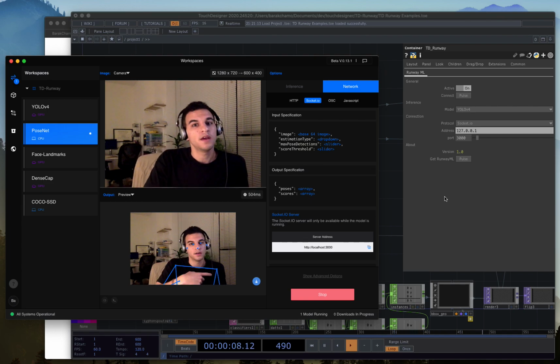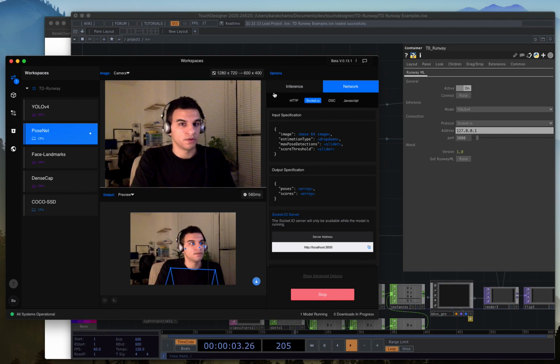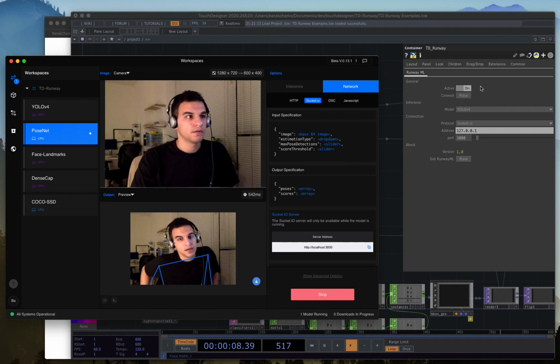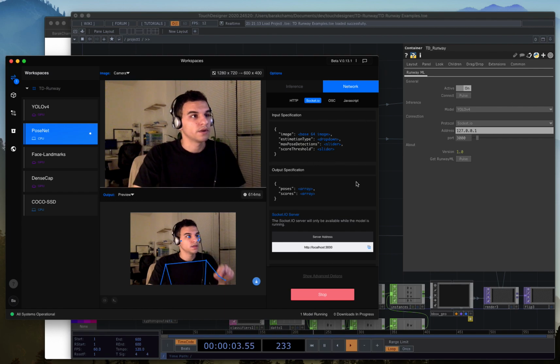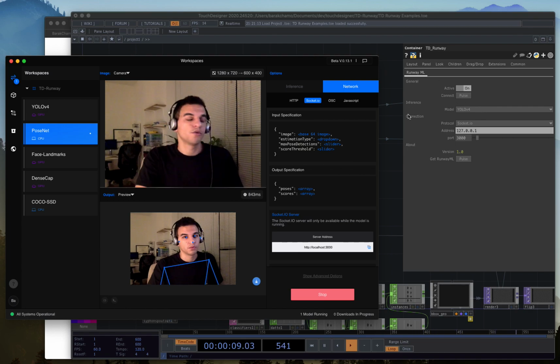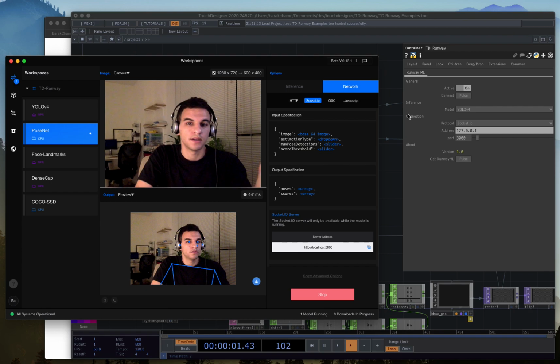So if you just open Runway and TouchDesigner, which you might have done if you ended up on this video, you'll see that you're not getting any data until you click the connect button here inside TD-Runway, which is one of the main reasons I built this thing, to avoid having to deal with the handshakes for every single model. You have to tell Runway that you're listening, otherwise it's not going to send anything for both Socket.io and OSC. So you have to press this connect button every time you run a model. When you stop the model and run it again, you again have to press connect. You only have to do it once as long as the model is running.